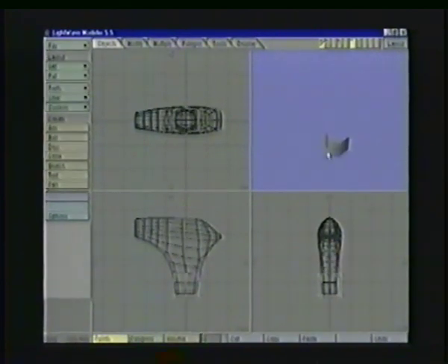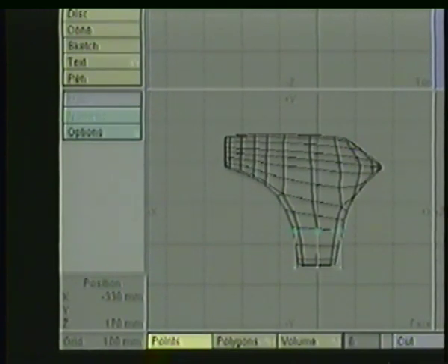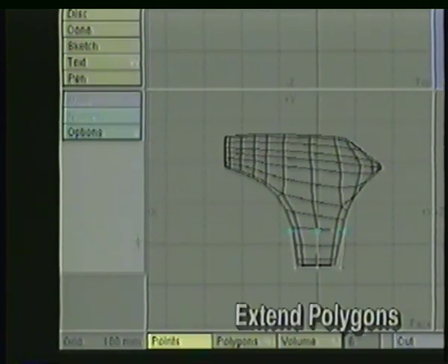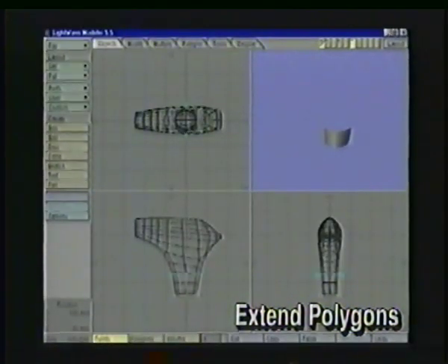I don't really need to work in MetaNurbs the whole time. I'm going to select with the lasso with my right mouse all the top points, and once again H on the keyboard for stretch, because I'm going to stretch these outward in the top view just a little bit because this is much wider than the base. Also, I'm going to deselect those points and reselect the points, this time in order. And by stretching those points out, it makes it a little easier to select just those points.